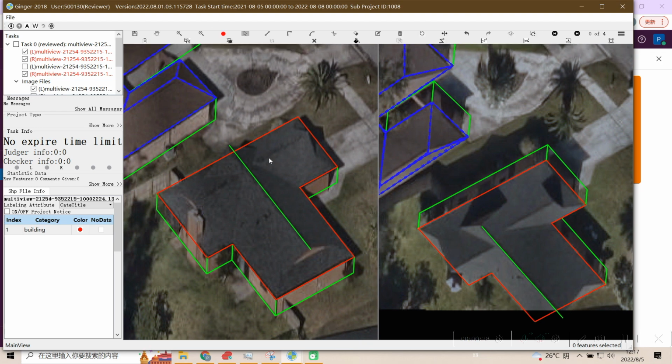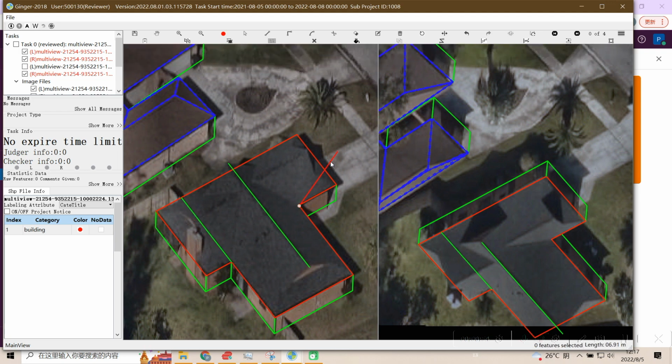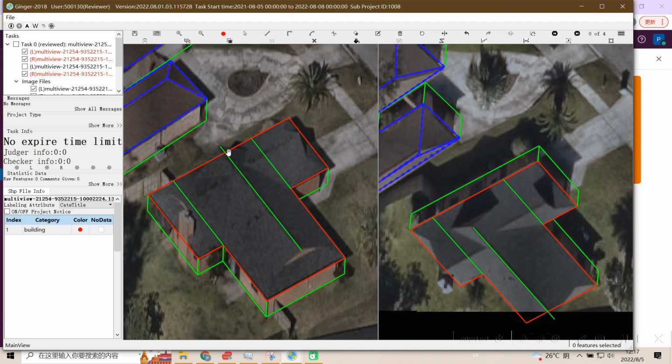So next, we're going to find out the corresponding footprint for the top or the highest roof ridge, which is the one in the middle, right? So we can draw two more assist lines to divide this building and get the corresponding footprint part for the top roof ridge. So after we have got this part out, then we need to find out the hip because